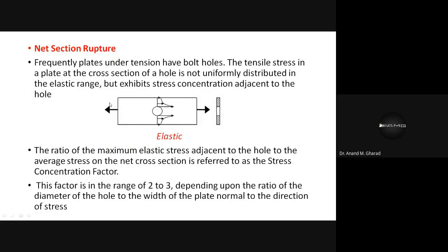Earlier, if you remember, we have not discussed these modes of failures, isn't it? We have simply said that these are the formulations for VDSB, VDPB, and based on that, we have calculated the number of bolts which are required. But after placing these bolts, naturally, these bolts may experience certain yielding. Also, the plate may experience rupture. So all these rupture capacities and the yielding capacities of the bolt and the plate are supposed to be checked.